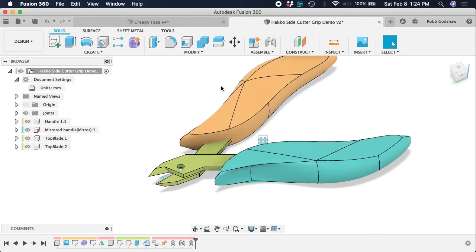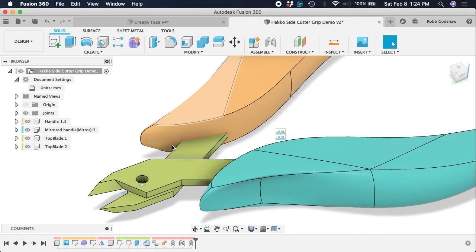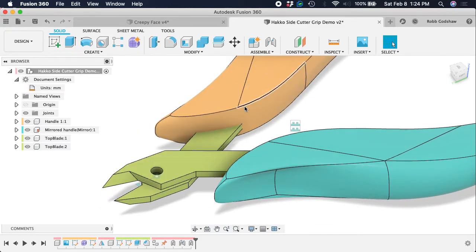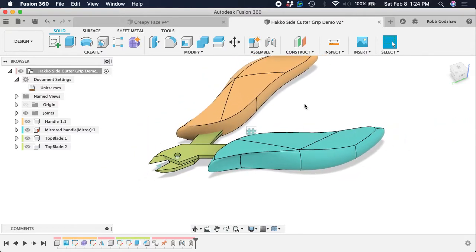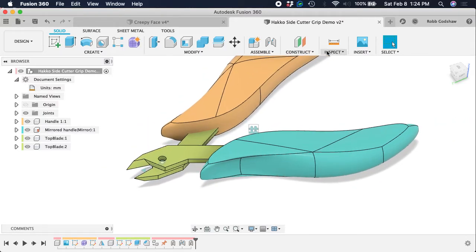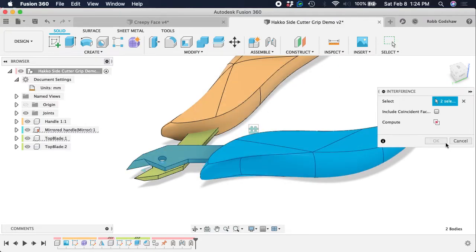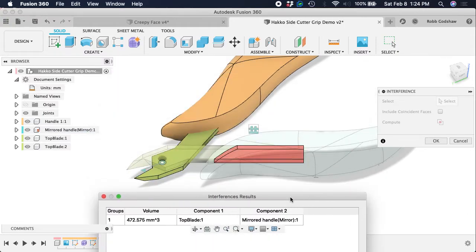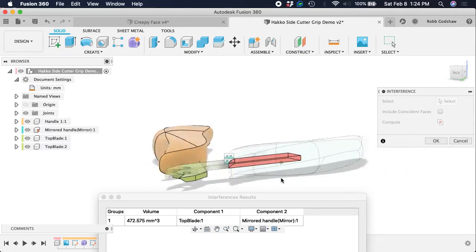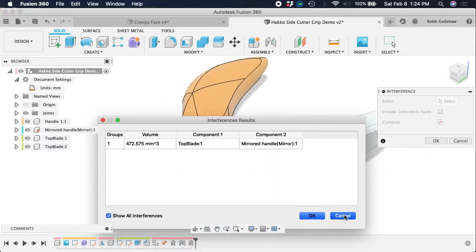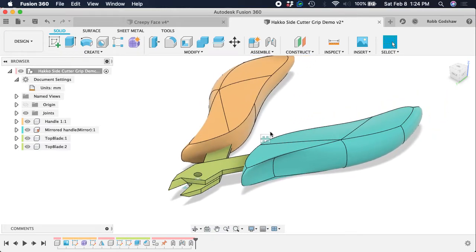It's kind of a jam-packed demo, but it's going to be online. There's two more things we have to do. We have to add the screw, and, anybody see a problem with this model as it is now? Yeah. These two parts have a little bit too much in common. We have to make that hole. And we have to add hardware. So let's make the hole first.